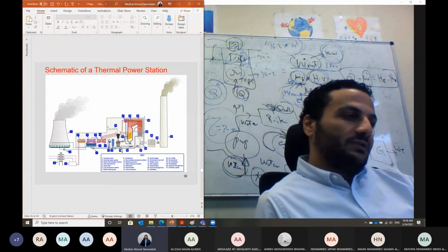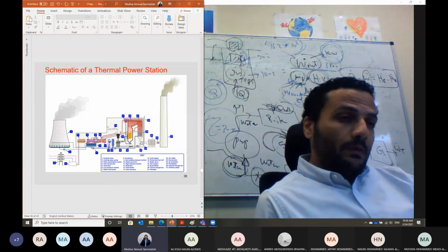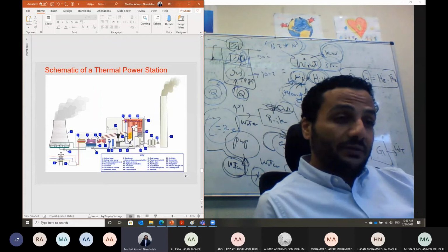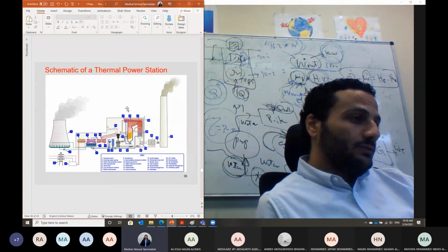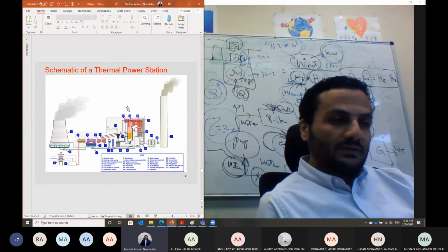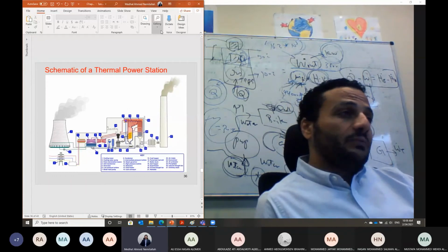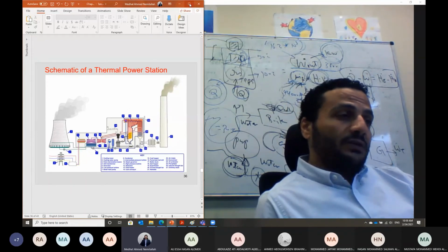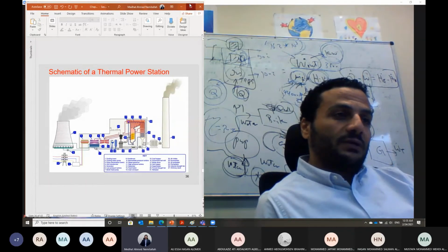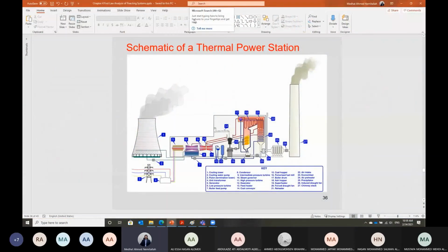Usually, if we shut down a steam turbine and run it back, it takes about 2-3 days of service until it gets back to service. But a gas turbine can just start immediately, so it is good to use the combination of gas turbine and steam turbine.